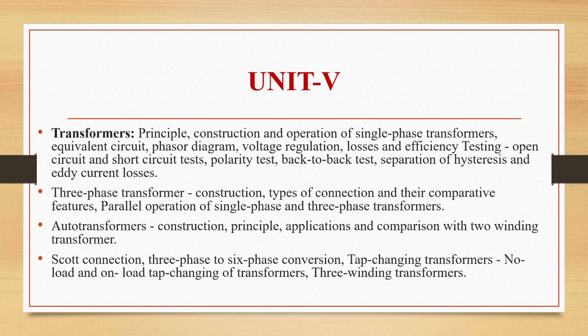Then we have seen the equivalent circuit. We represent all resistances, inductances and reactances in one circuit diagram for primary and secondary sides, and we also include the no load circuit in that equivalent circuit. Then we have seen the importance of each and every phasor diagram. We have seen what an ideal transformer is. An ideal transformer is one which does not have any iron losses, no winding resistance and no leakage flux. That is, flux will be confined to the core, flux will not leak.